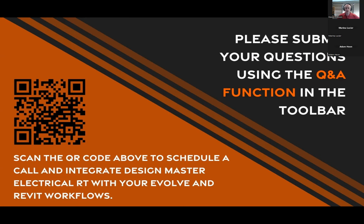And it's actually more interesting if you put in two curves. So we'll do LP3, because that makes sense. And then we're going to assign a curve to it as well. For something more interesting, we'll come here, give it a thermal magnetic curve. And then we edit that graph, put in LP3. And then you've got your two curves. They're not coordinated, so you have to go back and adjust that. So you can do all this in Revit, and the idea again is that you're doing all of this in Revit based upon your Revit model rather than doing Easy Power at all.